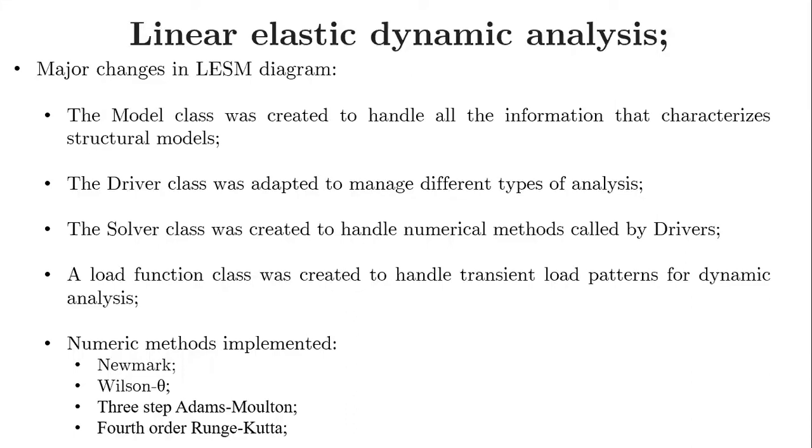The major changes made in the LESM diagram to include the dynamic analysis in its previous version are going to be treated here. Firstly, as I commented before, the model class was created to handle all the information that characterizes the structural model, and the driver class was adopted only to manage the different types of analysis. A solver class was created to handle numerical methods called by drivers, and a new load function class was created to handle transient load patterns for dynamic analysis.